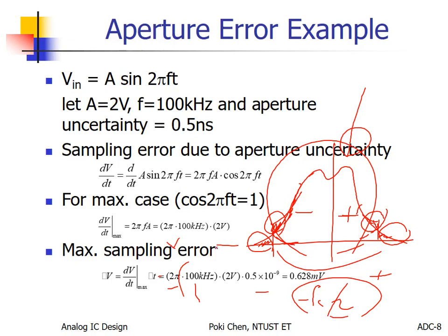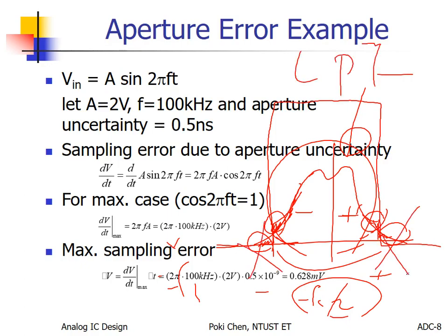Yeah, in theory, we can have this kind of low-pass filter to cut out all those frequencies our ADC cannot handle. Got it? And for this error, yeah, the higher frequency than 50% of the sampling frequency will be folded back to hurt your original spectrum. We call it aliasing error. Okay, yeah, in some place.